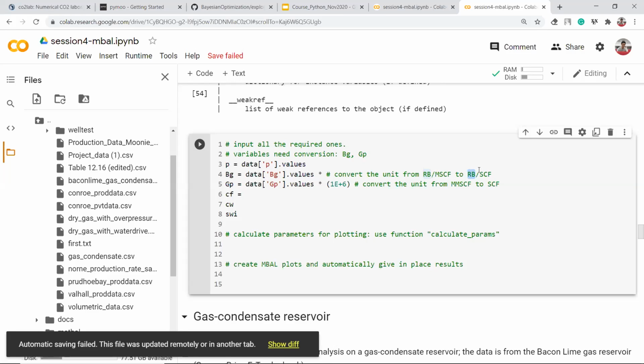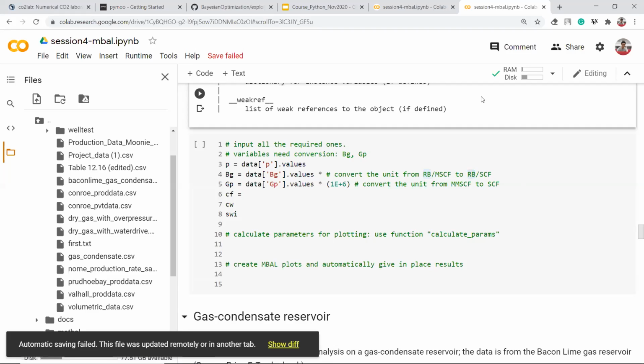It will expand. For oil, if we have, for example, 2 gallons of oil and you bring it into the subsurface, into the reservoir, you will have only 1 gallon because it shrinks. So if you want to be rich, you cannot go to the reservoir because you will lose your quantity. At the surface, the volume of oil will be higher than in the reservoir.